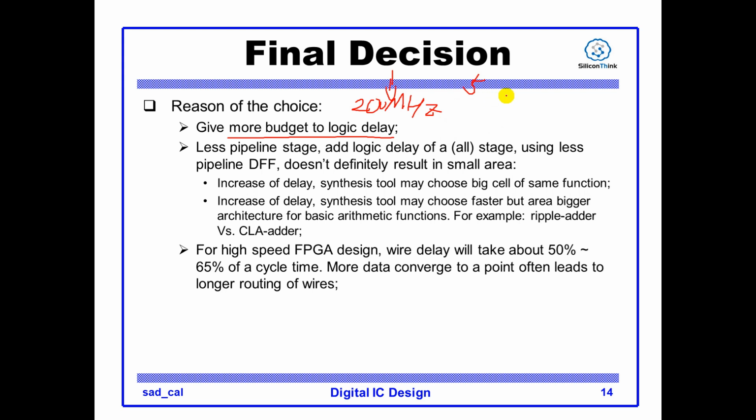You'd better estimate that the delay for this part is about 4.5 or 4 nanoseconds. You have to leave more budget for the logic delay.